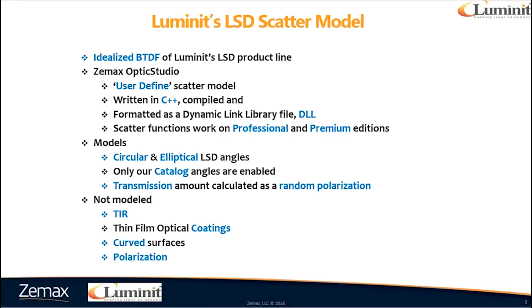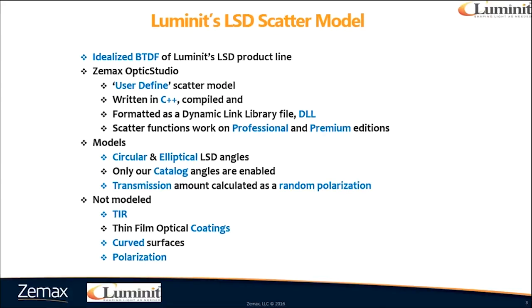We can model Luminit's circular and elliptical LSD angles. Only our catalog angles are enabled. For calculating transmission, light is treated as randomly polarized. Please keep in mind that TIR, coatings, curved surfaces, and polarization are not enabled in this model.